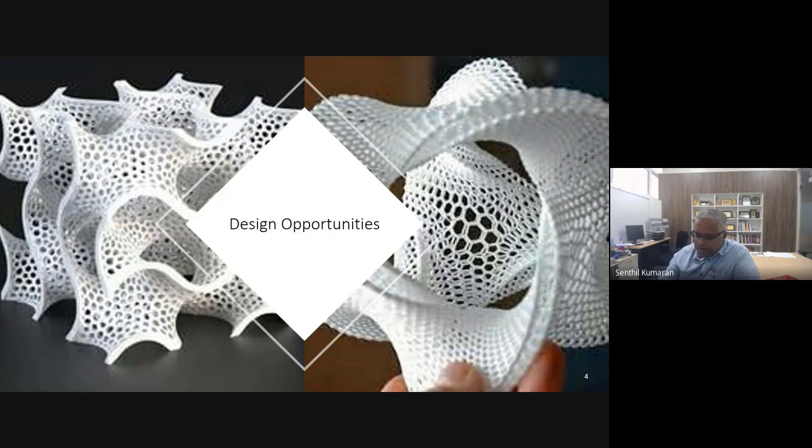Okay, so PLA is a biocompatible material. But PLA is not the solution for all problems. So PLA is good. It's biocompatible, biodegradable. So it's cheaper. It can be used with any type of printer, whether it's a consumer printer, a desktop printer, or a commercial printer. So not a problem. But it has its own problem. It has a quick aging property. It becomes stiff, so it becomes brittle. So yeah, you can mix and match anything.